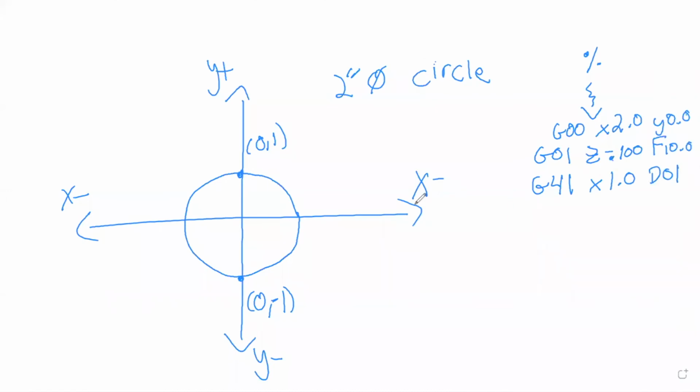All right, guys, we're going to do a quick example of using circular interpolation. Now, if you guys remember the key points, G02 is clockwise and G03 is counterclockwise. A couple other key points to remember is that we program using these codes to the end of the arc. So wherever our end point is of the arc will be our point.